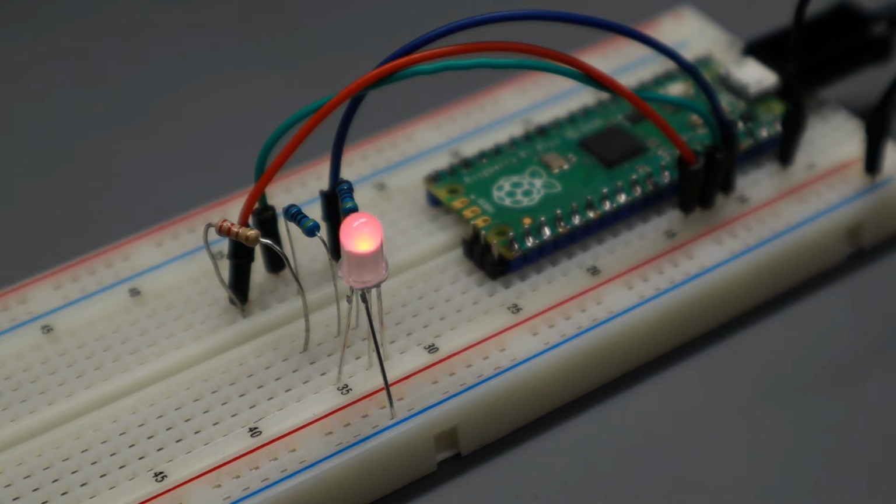Now, as you can see with the basic fade on and off with the single color portion, that's kind of a cool effect, and it's a little nicer than just simply going on or off. When we start blending the colors, we're blending the intensity of both colors the same amount, so it's more of an intensity of that particular color. You could also alter that intensity for just the red or just the blue and mix up your duty cycle change for each of the colors, and that would give you a different color or different shade of color.